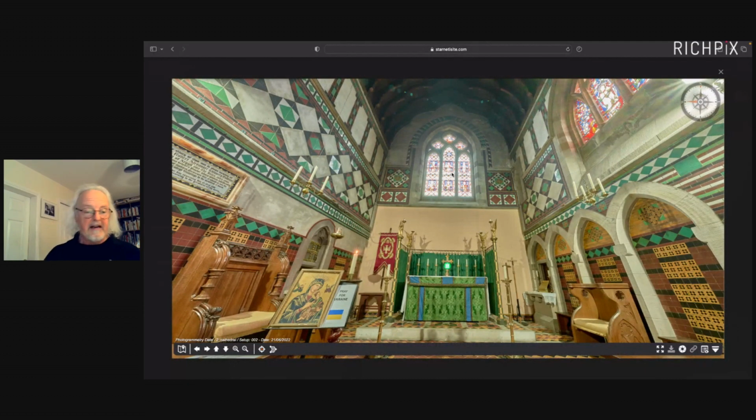Photogrammetry and point cloud colorization inside a building is always tricky, because you've got such a variety of range. That's the word I'm looking for. Dynamic range. You've got dark shadows, bright sunsets. Now, in this case, I'm okay because I only need to take one image. But the beauty of 360 is it really lends itself to doing a thing called HDR, or what I call 32-bit photogrammetry, where you can bracket and get homogeneous, perfectly lit, without all the detail hidden by oversaturation and exposure or clipping. But in this case, I didn't have to do it.